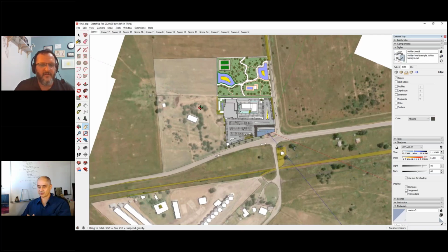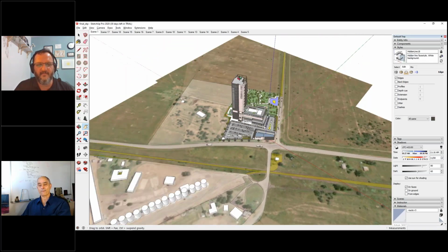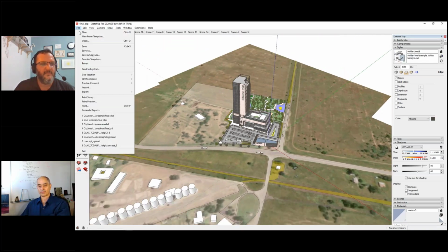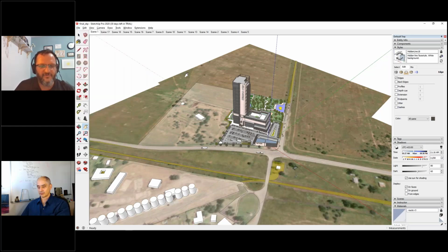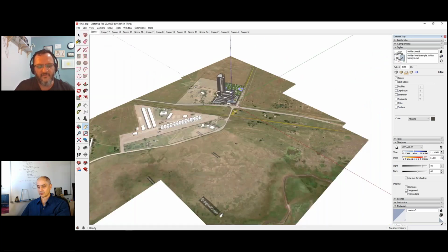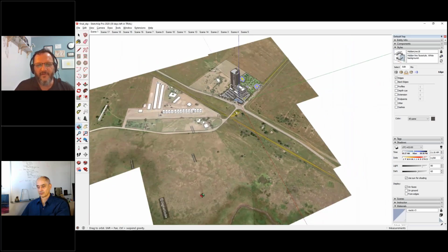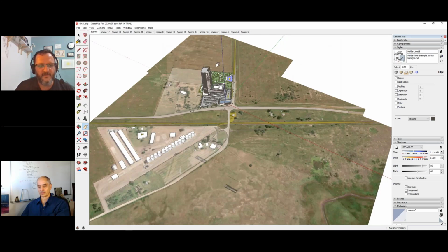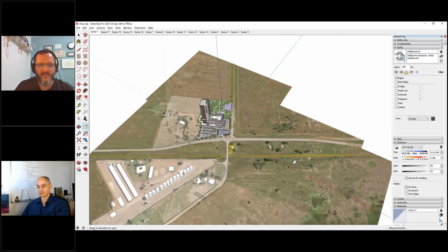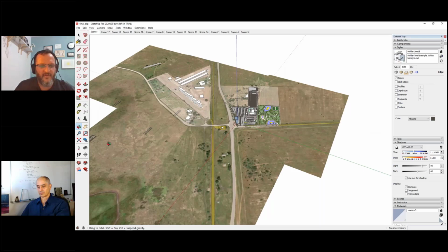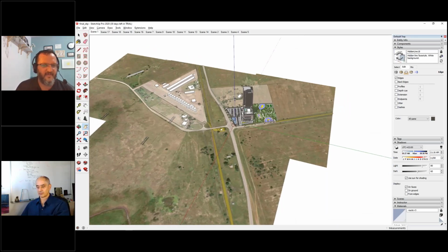Or the next, absolutely. Just one last thing I wanted to say, that in SketchUp here, we have something called geolocation, and you can go and add through Digital Globe any geolocation on the planet. It will import the surface for you of that region. This is a region in Southern Africa, so I imported it, and it's not as precise as a land surveyor's drawings.